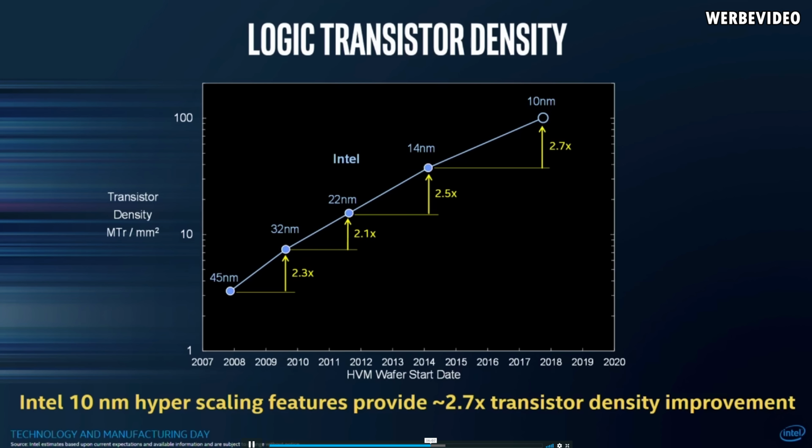And for example, if you compare the transistor density of Intel 10 nanometer, which is about 100 million transistors per square millimeter, with TSMC 7 nanometer, which is about 91 million transistors per square millimeter, you would assume that Intel 10 nanometer is faster, but that's not essentially true, because it depends how your transistors are looking, because at different parts of the CPU you have different transistors with different sizes and different shapes. It depends if it's a NAND cell, if it's an SRAM cell.